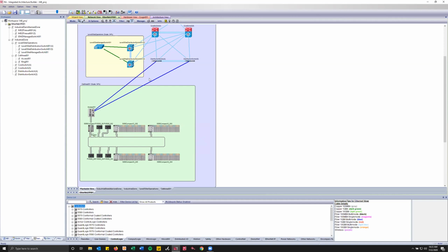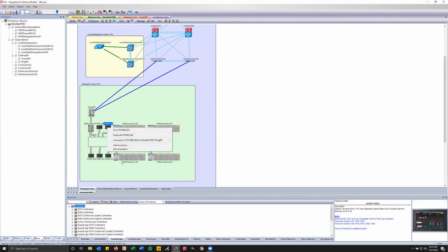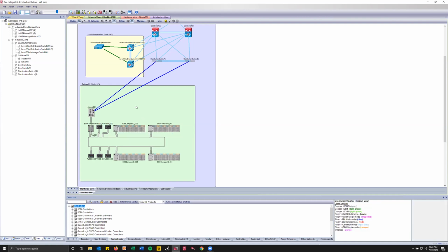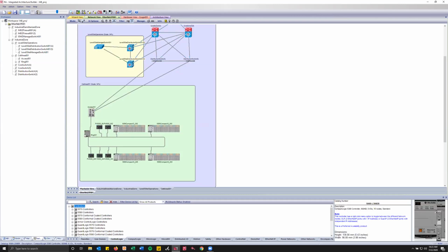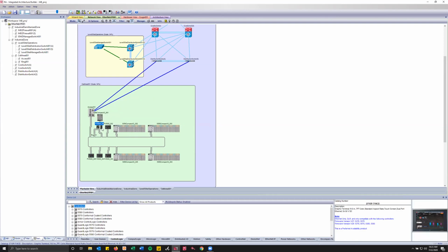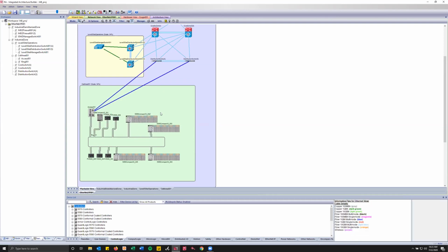And the other thing is, if you hold shift down, you can also momentarily view that connect mode. So if you just have to do something real quick and you don't want to fully switch into your connect mode, then you can just hold down shift and move anything you see fit that may need to be adjusted.